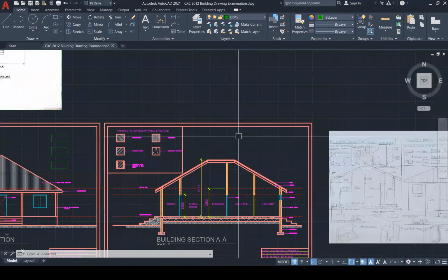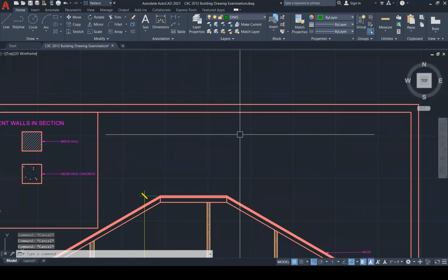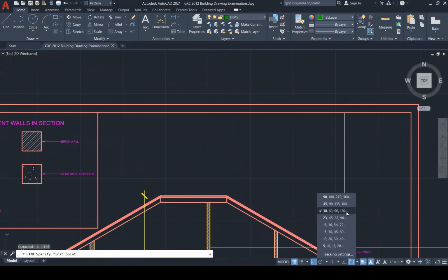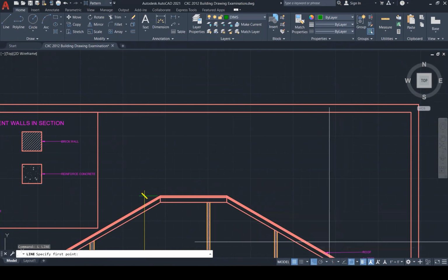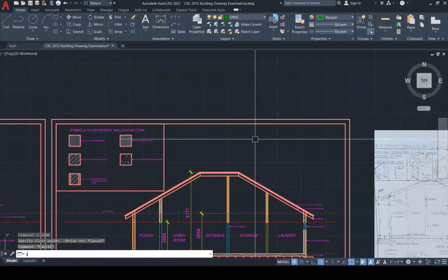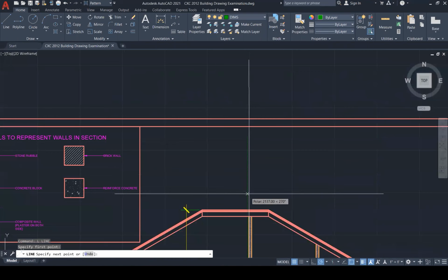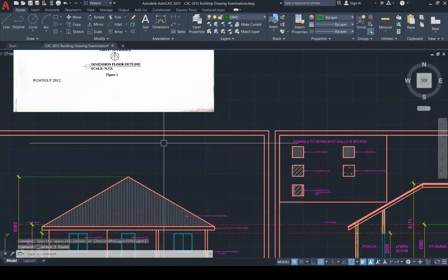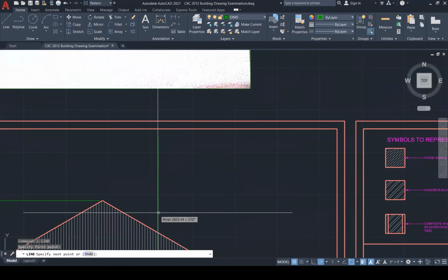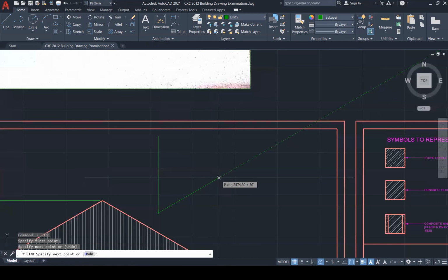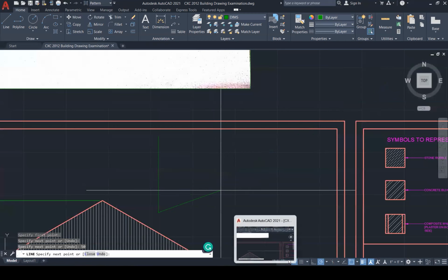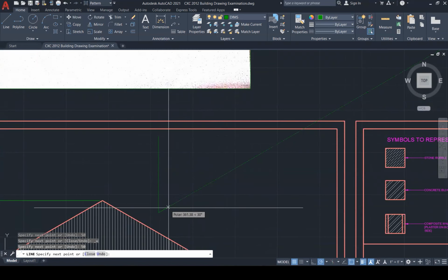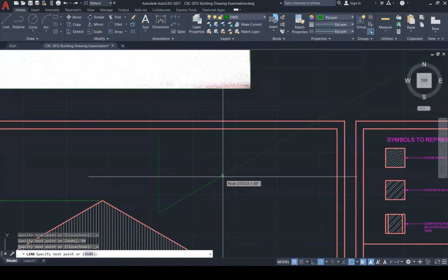So the first thing is you realize that these need to be all drawn as isometrics. So I'm going to go over and turn on my isometric mode. Polar tracking 30, 60, 90, 120. It's on, and I'm going to draw an isometric box and make this as easy as possible. So let's start here. Let's use a distance of 50. It's too small. Probably like 500.